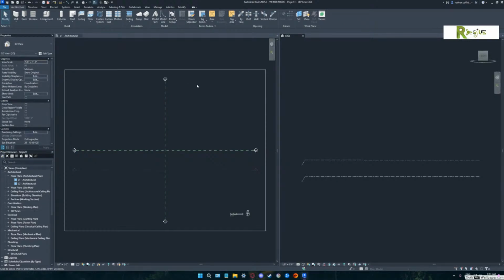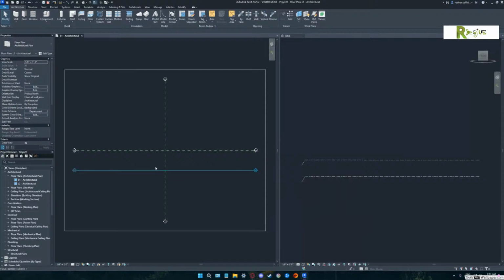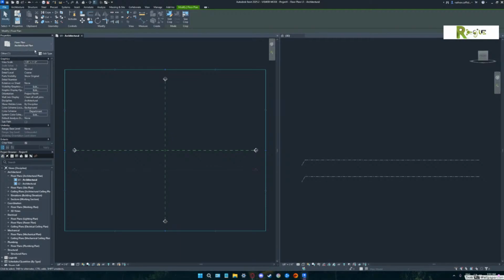So over in the plan view, you see your north arrow and your scale. I want you to delete both those the way I just told you. So pick on them and hit the delete key on your keyboard. So there's still a box in that plan view. You see the box around the outside? Pick on that. What is it? You see how that's named other, and we look down on it and it tells me what scale it is. That is the crop boundary.